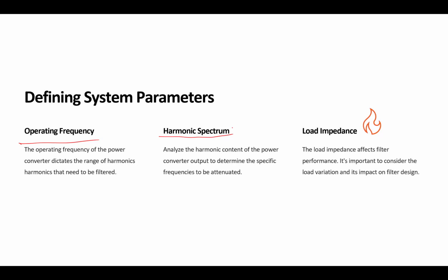Make sense? And if you have a maximum amount, for example, because we said the amplitude decreases as frequency increases, at a certain level those standards define the cutoff. At a certain level, you let go of the other frequencies. It doesn't matter. You neglect them. Now, I said practically filters do not mitigate very high frequencies because of that parallel C, that radiation factor that comes into play.